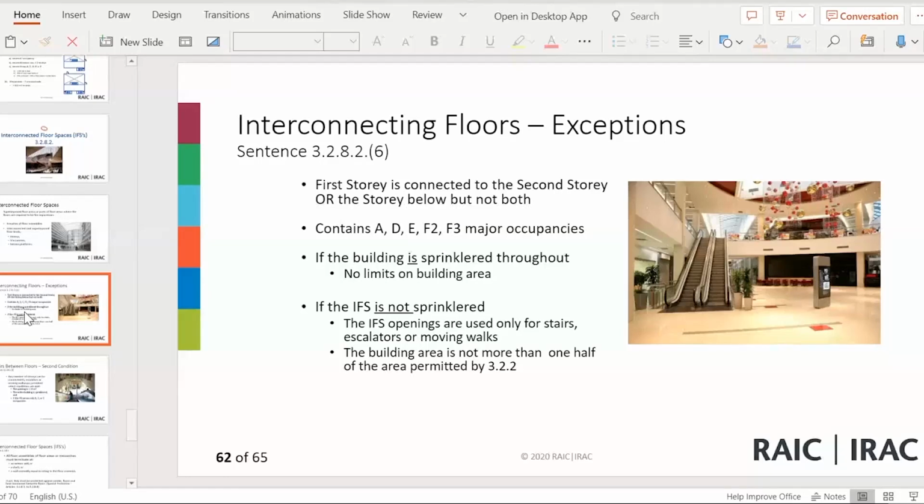Look at some of these examples of building construction where there's specification for the mezzanine rating, fire resistance rating, or fire separation requirements. And remember, sometimes we have fire separations with no fire resistance rating, and sometimes we have construction with just a fire resistance rating with no fire separation requirement. So I want to take you step by step into 3.2.8.1. So normally there's exemptions and application.